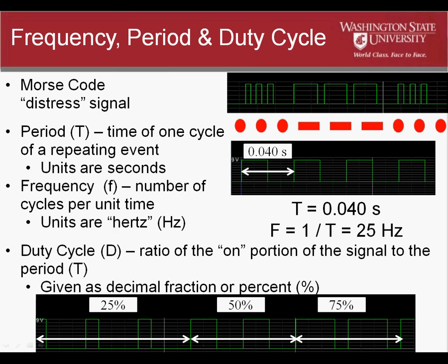The concepts of frequency, period, and duty cycle cut across engineering disciplines. We'll see how they are applied to voltage control of motor speed, and more specifically, how this changes the power delivered by the RCX to its outputs. Other applications of these concepts occur in signals associated with communication, load and fatigue characteristics and structures, welding process control, and many others. In electrical terms, a square wave is generated by opening and closing a switch. This concept is an underlying principle in communications and computer processing.